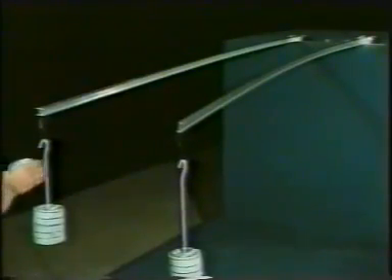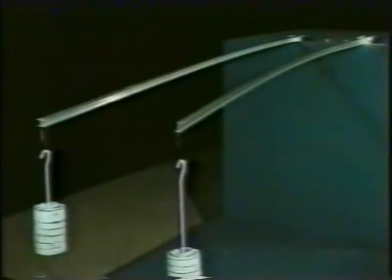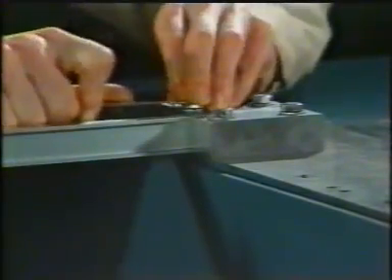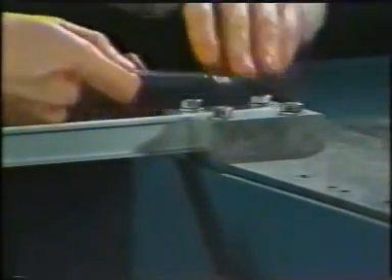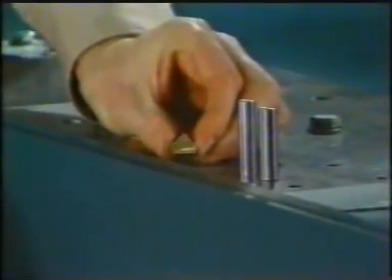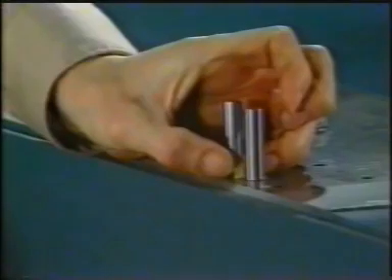Lateral torsional buckling is only likely when a section has significantly different values of second moment of area and is subjected to bending in the stronger plane. So far, little has been said about the end conditions of the beams. As with columns, the end conditions have a considerable influence on the stability of the member. This support is fully fixed and restrains all component distortions, whilst the one on the right is a simple support which permits rotations in both the vertical and the horizontal planes.